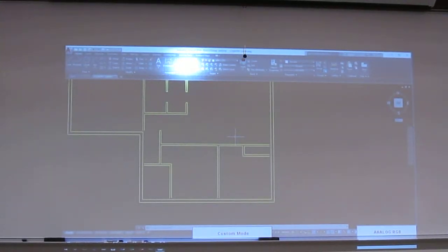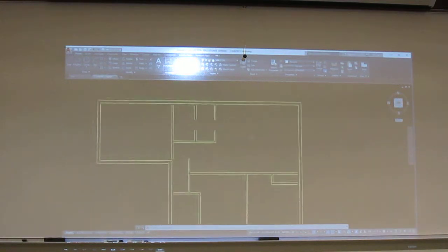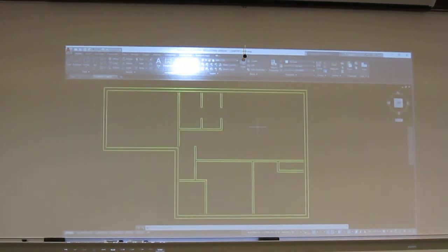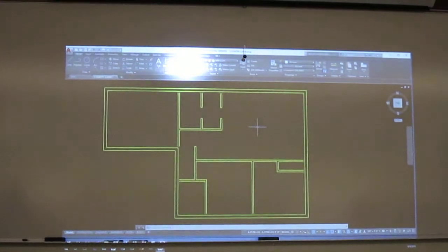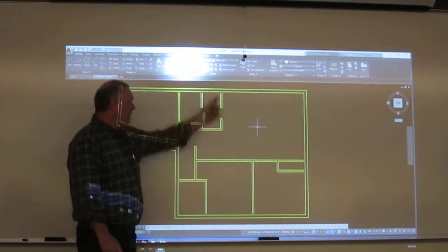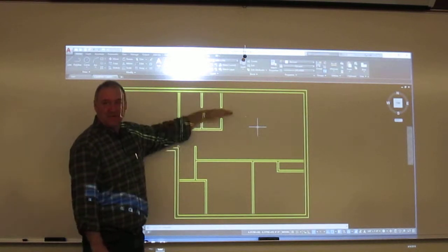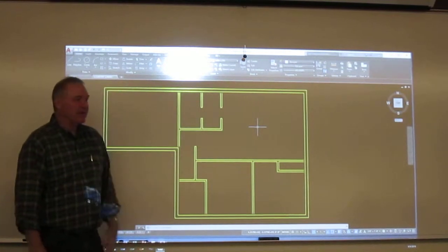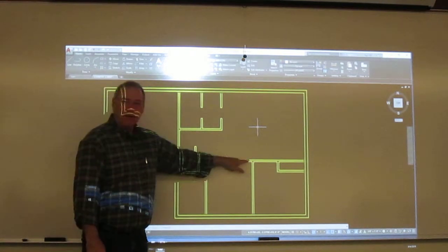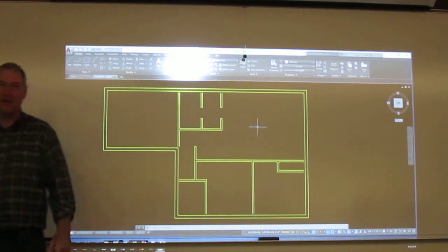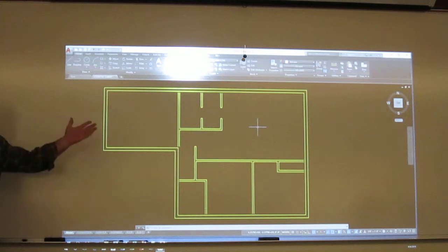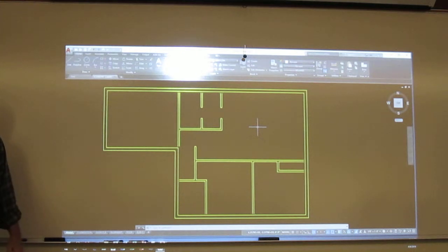Okay, so here's my basement plan, which is somewhat incomplete for this one, but in essence, we ran our floor joists in this direction through here, and most of us turned this wall, or if you had stuff flipped, this wall into a bearing wall to carry our floor joists, and we needed a detail of what's going on with that. Now, our full section caught that when we drew that in the basement floor, but we never really talked exactly about how that is done, and so I wanted to cover this.